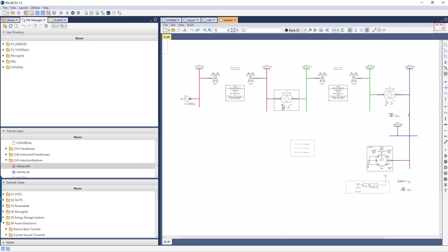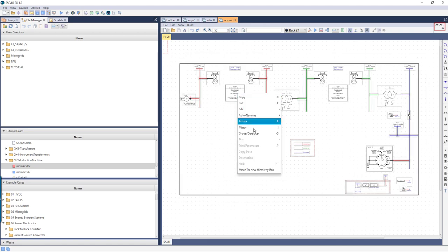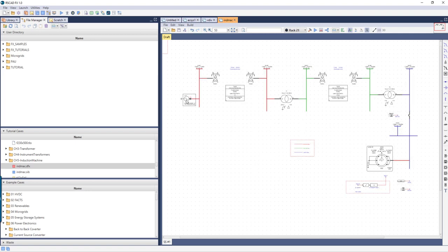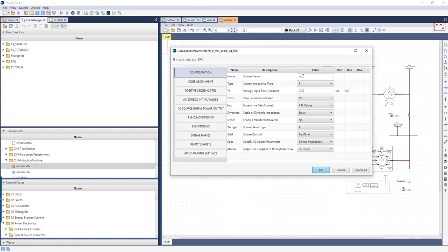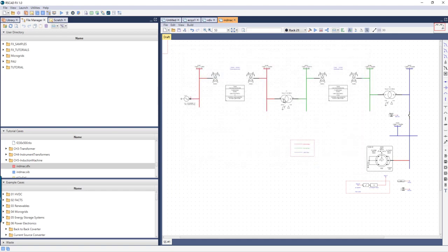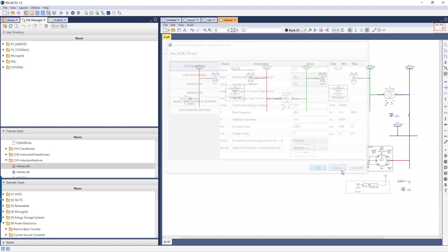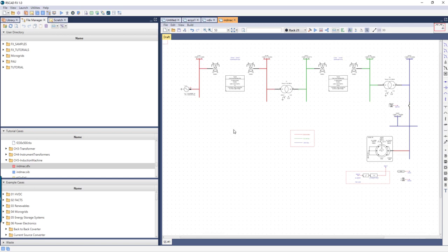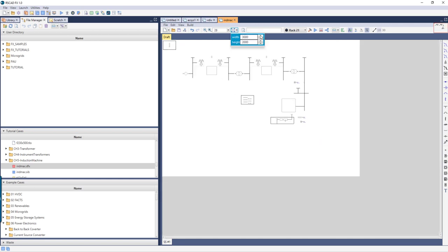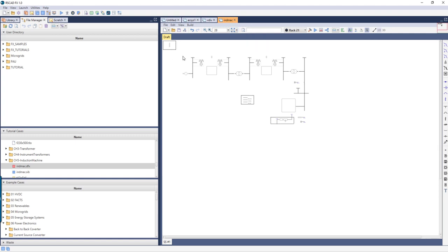So first I'm going to select the circuit and flatten the auto naming so that the pre-existing enumerator values are now included in the flattened parameter names, and a new enumerator has been added to the ends, and that happened for every component. And now I can zoom out, and I'll increase my canvas size here. And I can use control and drag to create a copy of my circuit, keeping in mind that auto-naming incrementation was turned on when I did so.